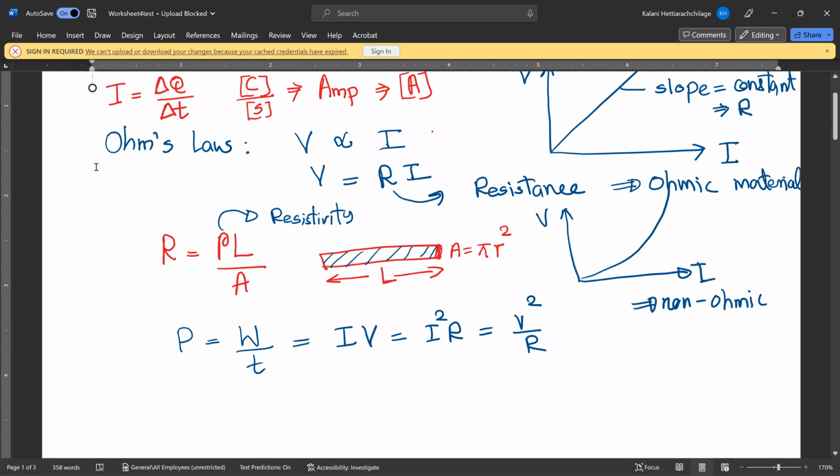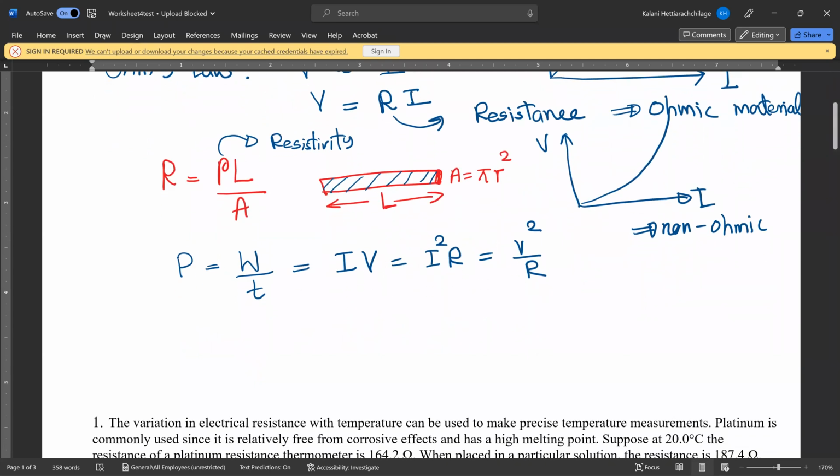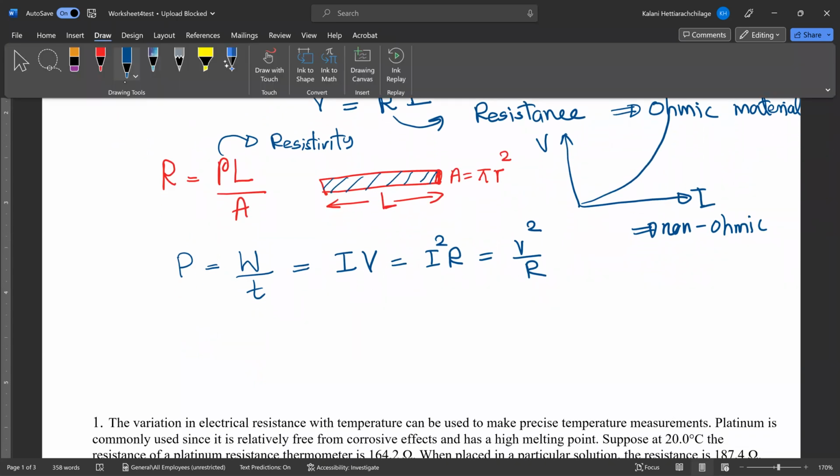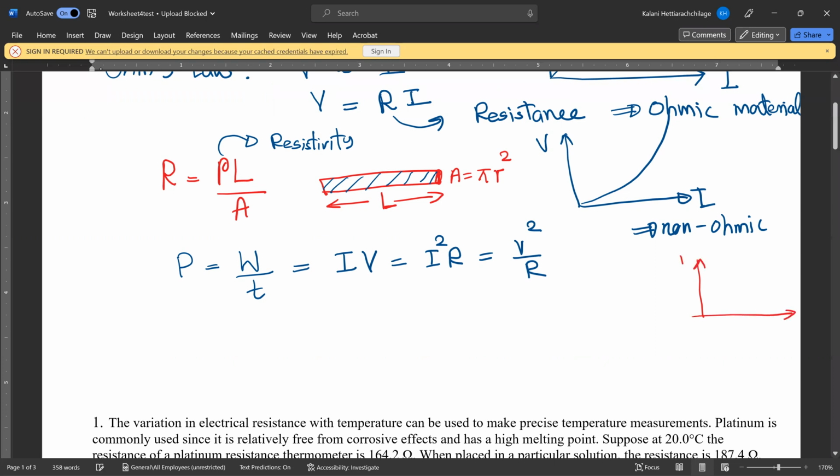So now, in addition to that, I discussed a very important thing in here about the RMS value. RMS, we call it the root mean squared value. The reason is, if you are using DC, meaning direct current, direct voltage, that means you basically have a graph where if I plot the current or voltage as a function of time, this is just staying constant. In that case, whatever you are measuring by using a multimeter at your laboratory will be directly the voltage and the current of the circuit.